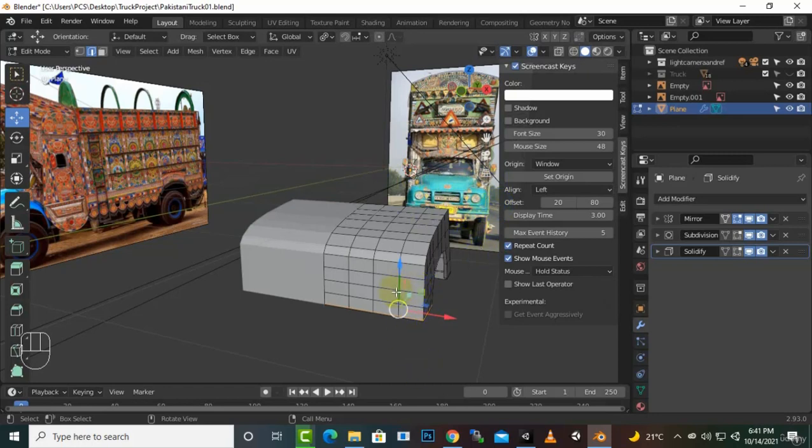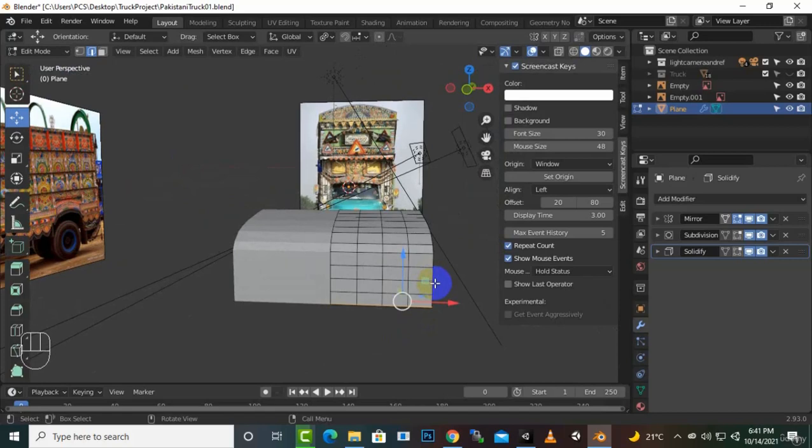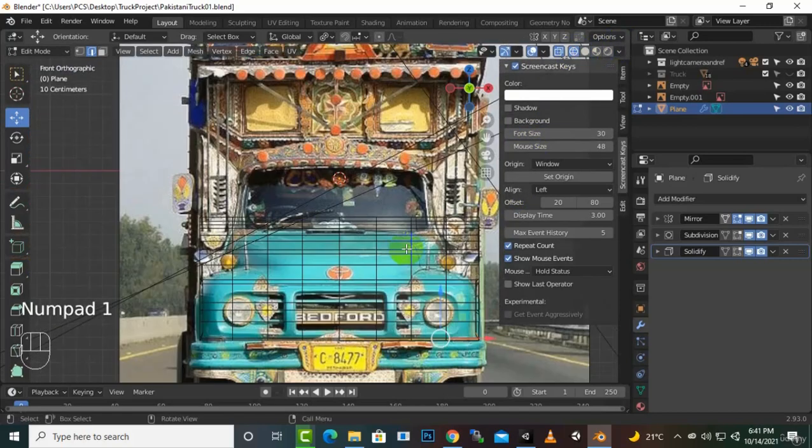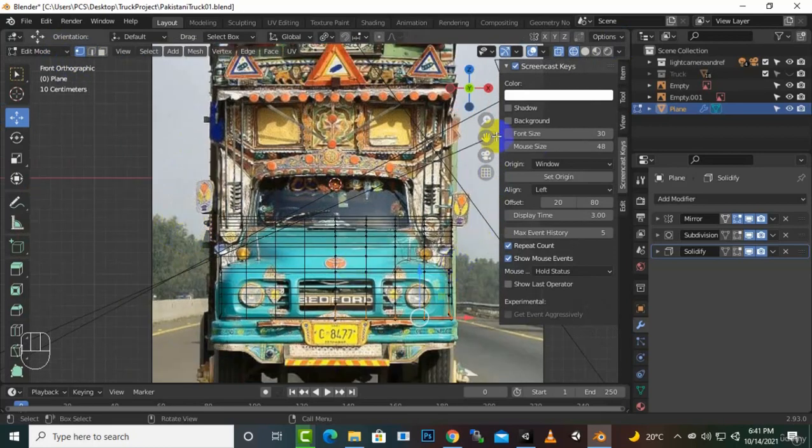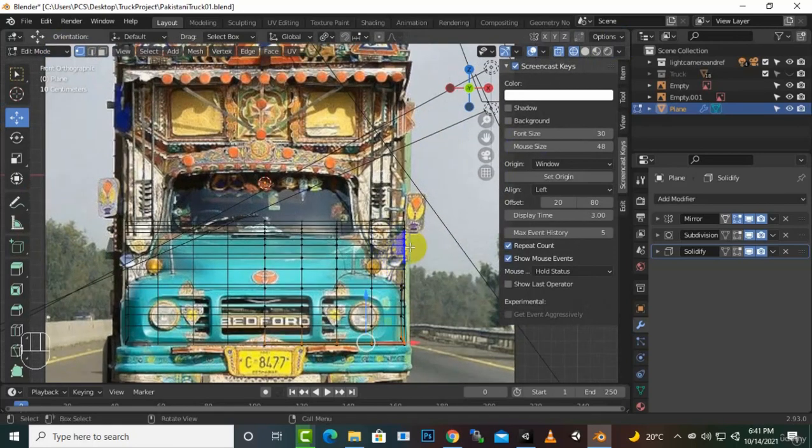So basically we will keep this section the same, and if we go to wireframe mode, you can see that we can just organize these things if we want to do so. So we will just arrange these by selecting these vertices, and we can move these vertices inside as well for a better shape. So I think here you can see we have inside and then outside.